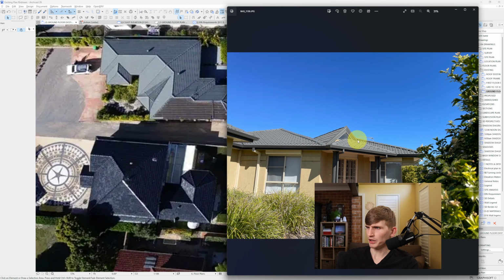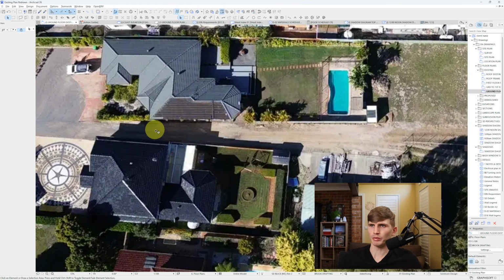So we've got a hip coming down through here, hip here. It looks like we've just got a gable and another little gable-ish type roof just out the front here. So we'll break this down and we'll create it with a couple of different roofs. So we'll separate 2 new roofs here and just keep this as the primary roof plane just here. So it'll make sense in a second.